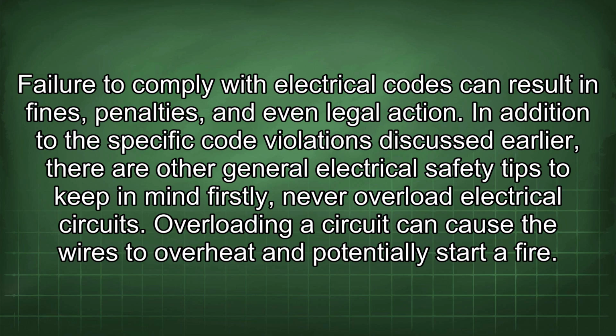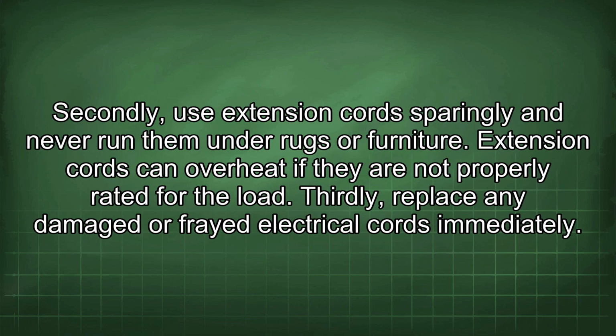In addition to the specific code violations discussed earlier, there are other general electrical safety tips to keep in mind. Firstly, never overload electrical circuits. Overloading a circuit can cause the wires to overheat and potentially start a fire. Secondly, use extension cords sparingly and never run them under rugs or furniture. Extension cords can overheat if they are not properly rated for the load.